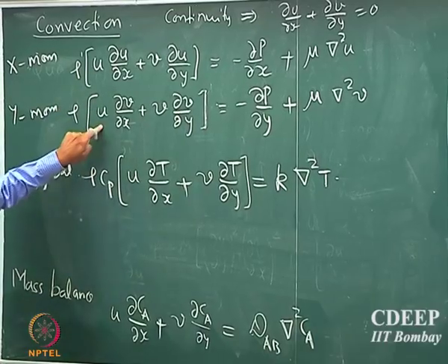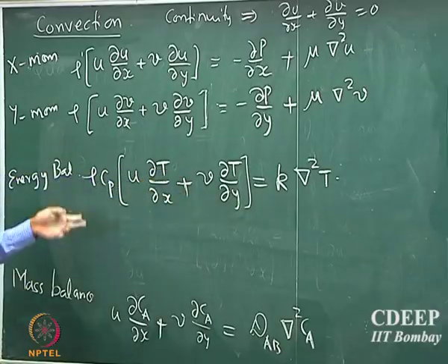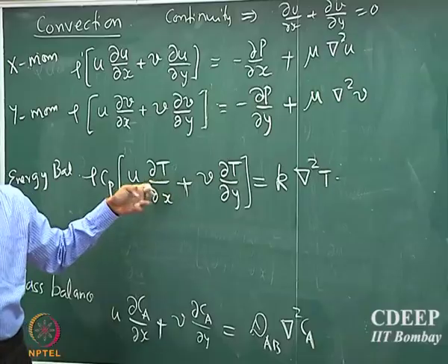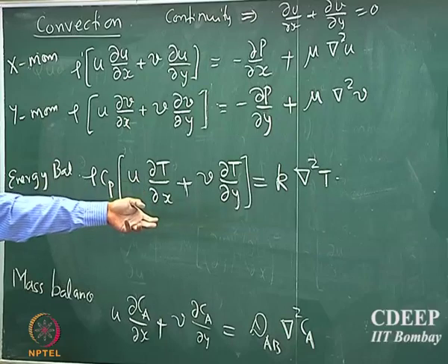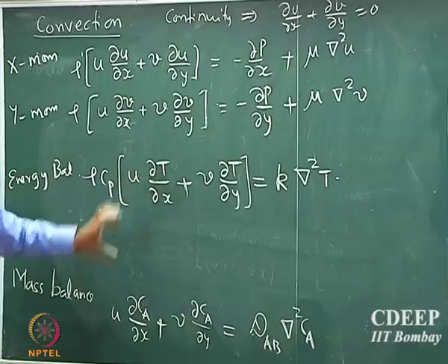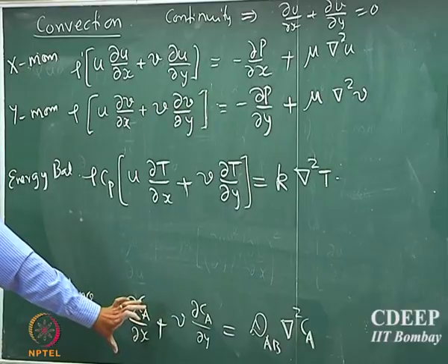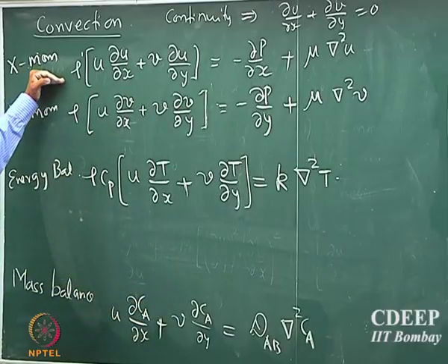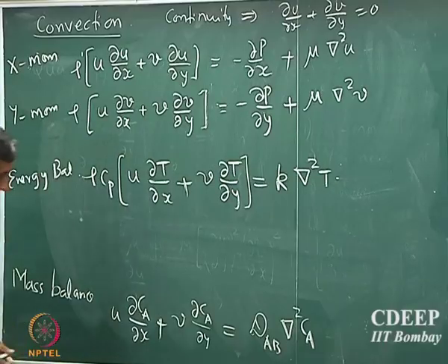So if we assume that the viscous dissipation is 0, then U and V are completely independent of the temperature, right. So if viscous dissipation is negligible, then U and V are independent of temperature, and therefore these two equations are linear with respect to temperature and concentration. So the real task is to find what is U and what is V. If we know that, we know exact solutions of this. Okay.